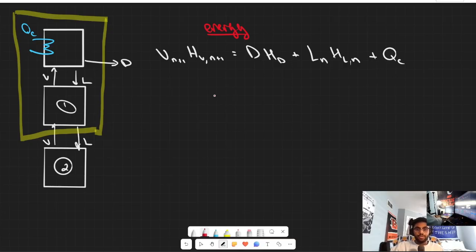Right, so now we can do the mass balances as well. And the mass balance is going to be quite analogous to our energy balance, where instead of the enthalpies, we're going to be focused on the mole fractions. So again, we have that vapor flow rate entering from the bottom, V(N+1), and then we're worried about the vapor mole fraction of that stream from that stage.